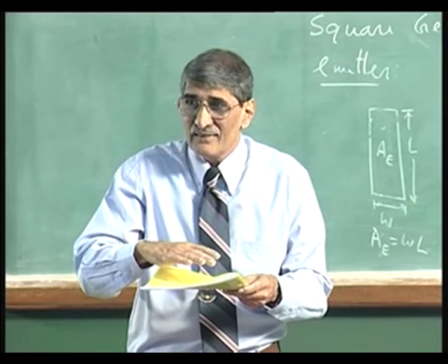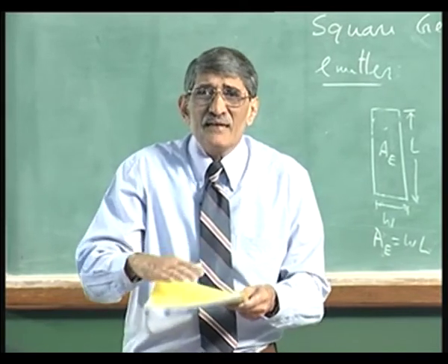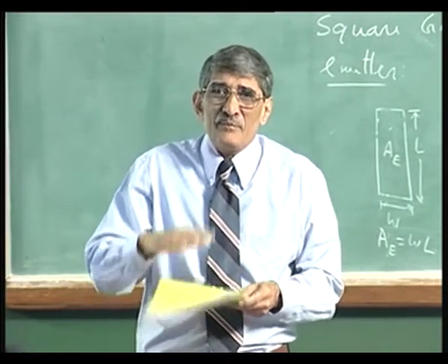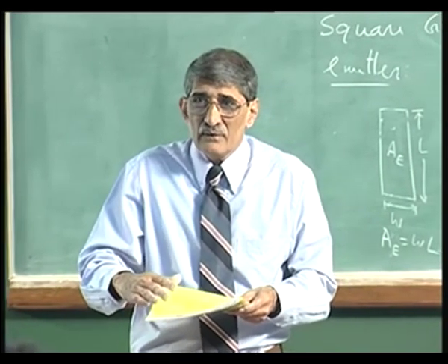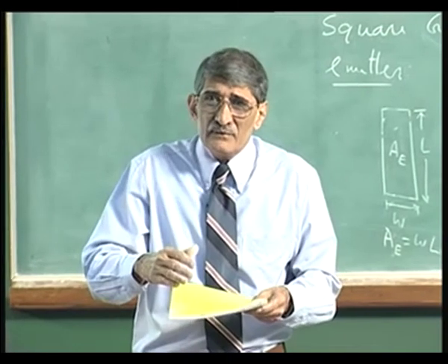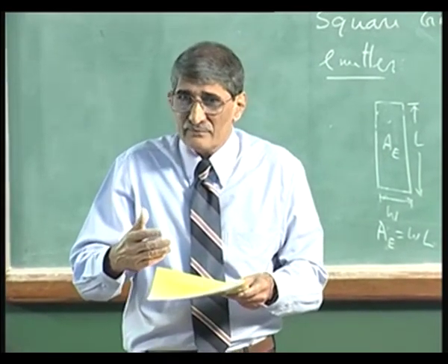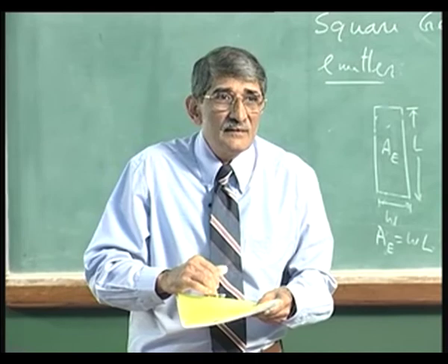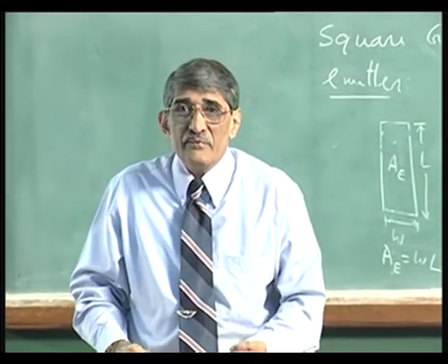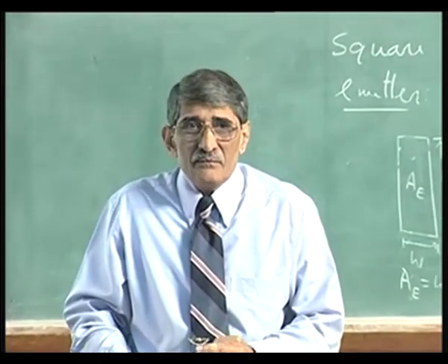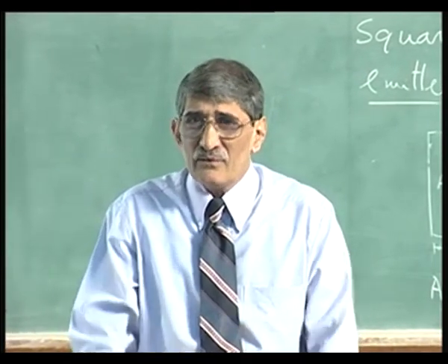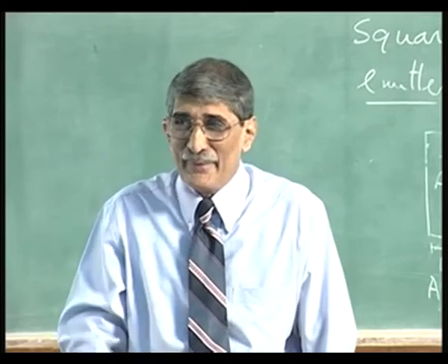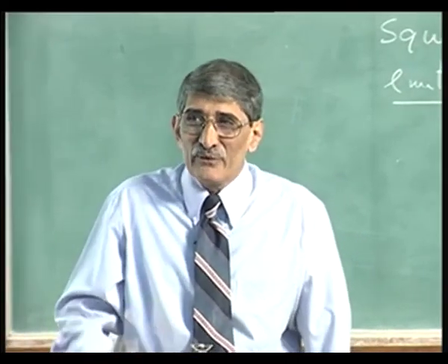Here, you deposit, it is just lying on top, that silicon nitride layer. You are happy about it, but you make a cap and measure the beta, still not good. Even if it is good, it is not so stable, because the dangling bonds are still there. So, here came the Bell Lab people finally realizing that you need to do some chemical treatment. So, they started dipping in all chemicals.